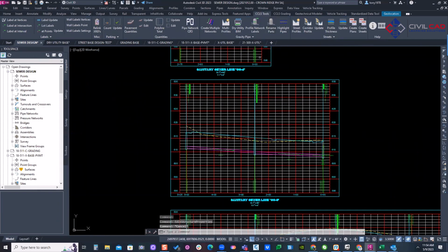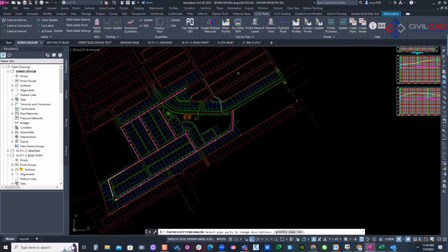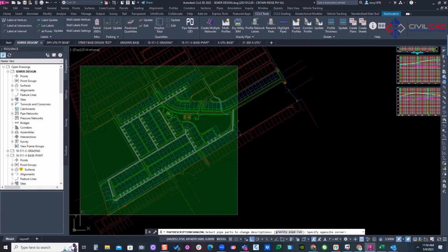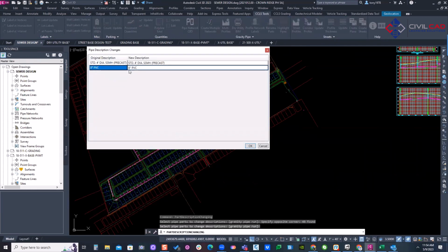So it's a simple little tool. And maybe I want to relabel all the pipes. So all the ones that say 8-inch, maybe that's, I don't know what it is. If it's C900, that's probably for water, but what it is for sewer. I can come in here and say, make them all STR 35. So all the pipes say that.